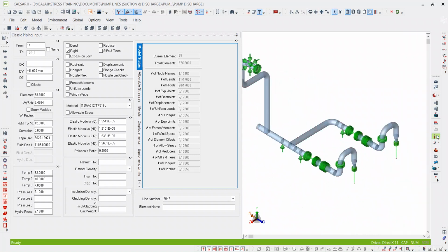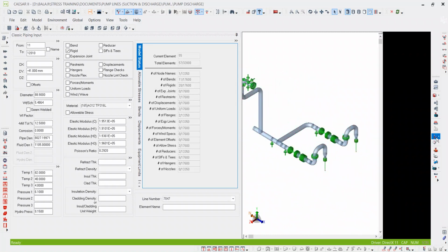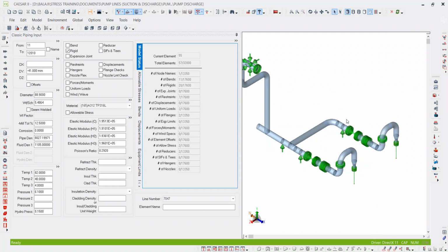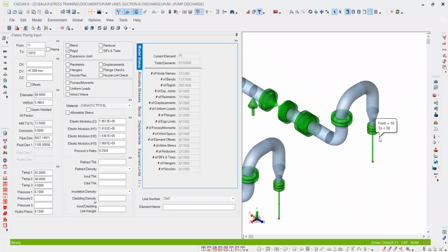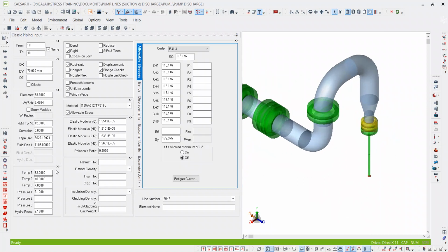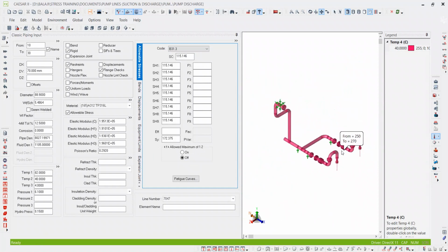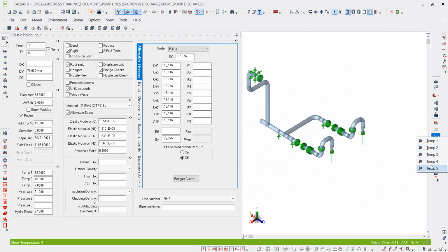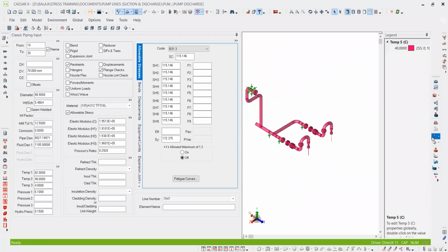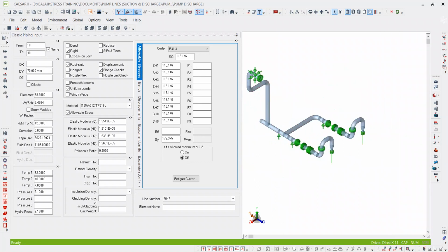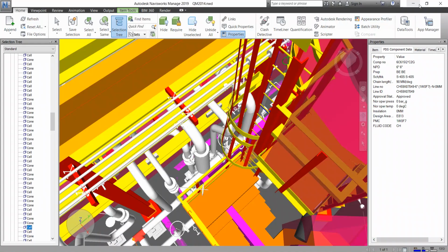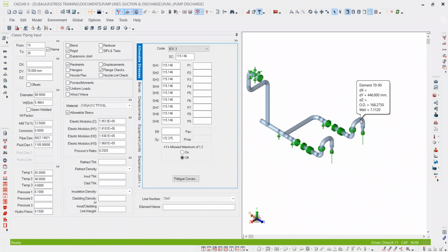So now what we need to do, we need to assign T4 and T5. Since we have copied this file from the suction line, we have assigned the temperature for T4 and T5, but we need to change accordingly. Here if you check T4, all over 40 degree only. And T5 all over 40 degree. So now we need to see which line we have considered for suction.